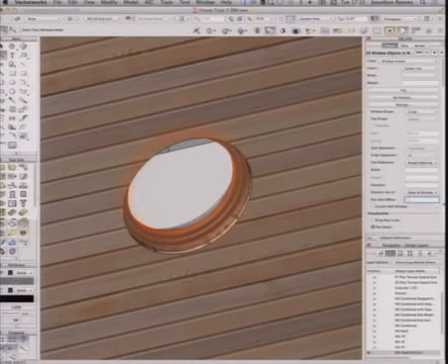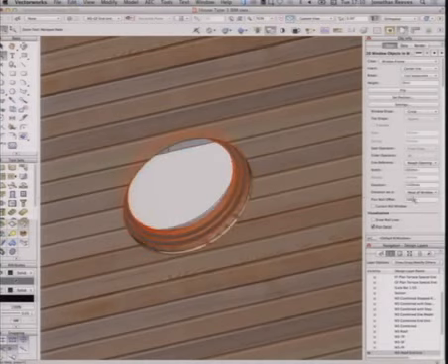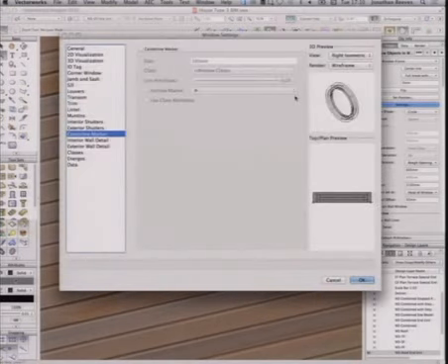I mean, yeah, definitely. There's lots of options. I can essentially push them forward or into or out of the wall using this thing called plan offset and wall. I can obviously put full width jambs on for a window like that. I certainly would. And yeah, I haven't shown you that, but there's also within the settings a wall returns button. Again, to return the brick or the block. You can do it, yes. And it all takes a little bit more time than I showed you today.